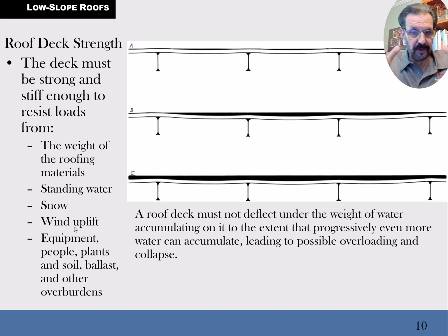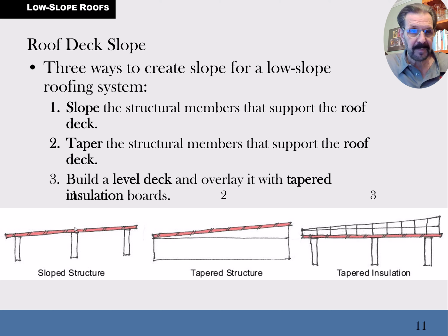And we can have a strainer around that, and that helps some. It helps a lot, but it's not permanent. Eventually enough leaves clogging up there will cause a big pond of water up there, and then eventually it will find the leaks where it can drain into and start causing water damage. But oftentimes with heavy enough rain, the drains can't keep up with all those leaves on top and they can collapse the building.